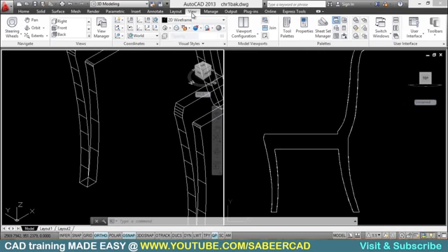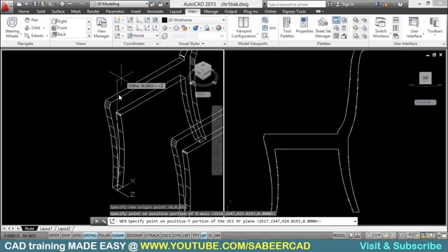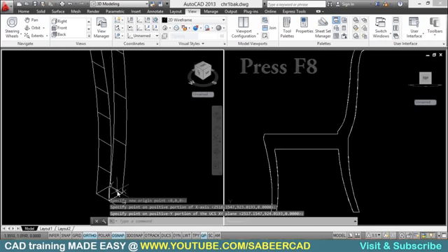I'll go to the View tab and select the 3-point option of the UCS command, and I'll keep my origin here, X in this direction, and Y I'll pick all the way onto the top by activating the ortho mode. Just click on that. Now the UCS is aligned on this face.